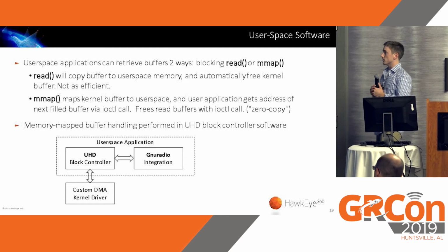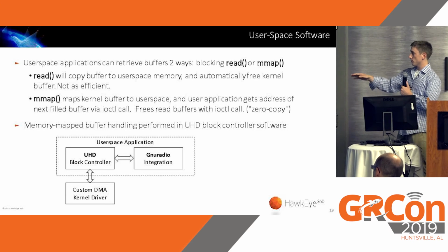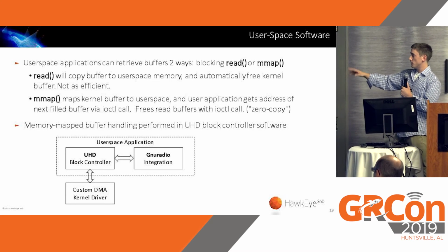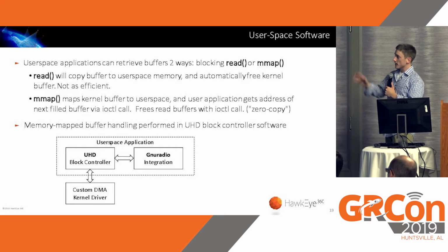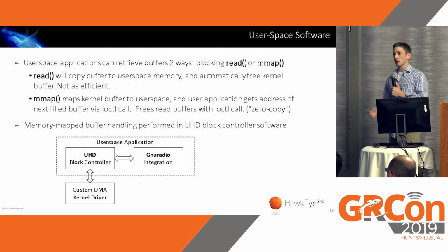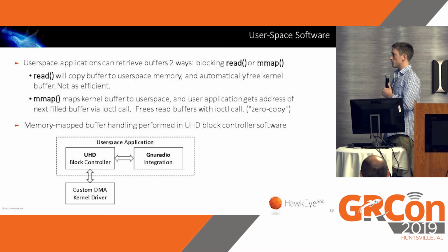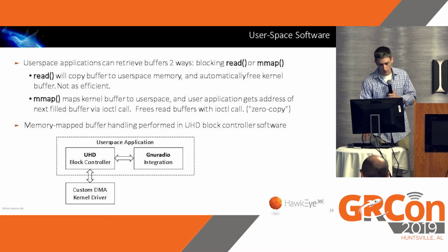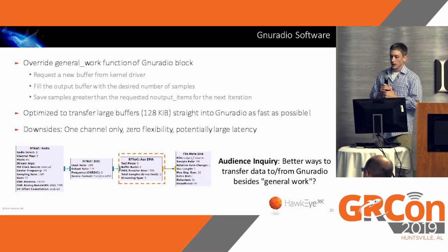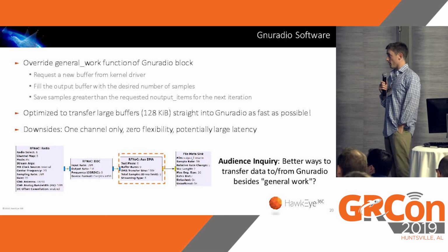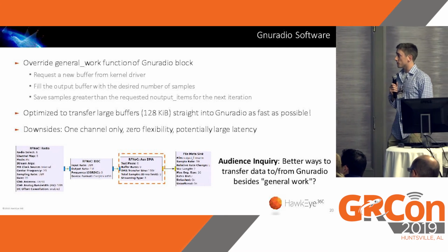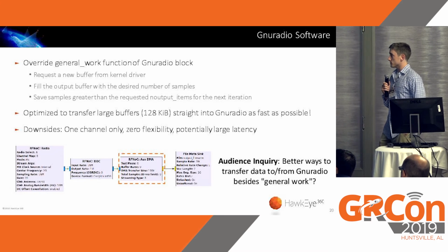So how exactly does this look? UHD holds our block controller that interacts in user space with the custom kernel driver. And then on top of that, we have a GNU Radio hook that grabs the block controller and is able to pull stuff into GNU Radio. And that leads me directly into this slide, one additional level higher, which is how we do GNU Radio with this.